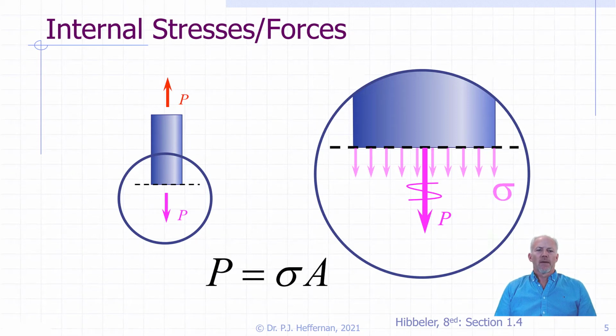and reflects this relationship between stress and load. Well, you're not required to memorize formulas in this course. This is a perfect example of a relationship that you just need to understand and know if you are to explore more complex issues. One note, this formula reflects, in the case shown, the average stress. Where we are close to the point of load application or have other geometric discontinuities near where we are examining, it is very likely that there will be higher and lower stresses across the cross-section. This concept that I'm talking about is St. Venant's principle. For our purposes in this course, we will be primarily looking at average stresses. Stresses, in effect, exist at a point, but we will be looking at the average stress across the cross-section.